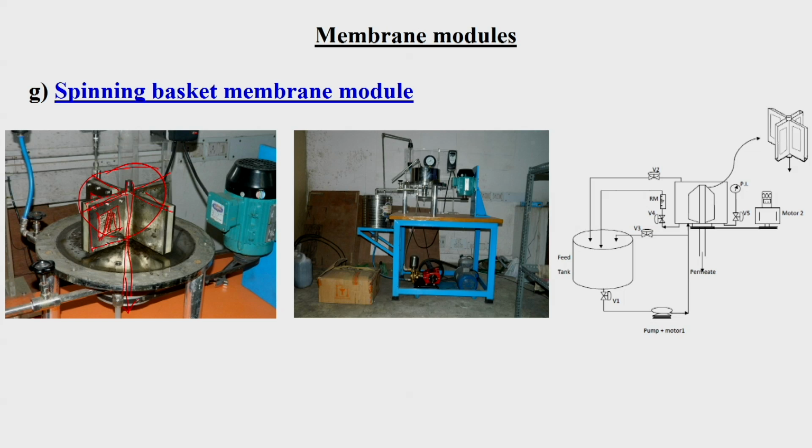is the rotor of the agitator. Whenever we place this membrane module over a tank like this, through there we put the retentate line, and the feed is entering from the bottom of this system, like this is the feed line. So, feed is coming and entering through this hole, and initially it will fill.